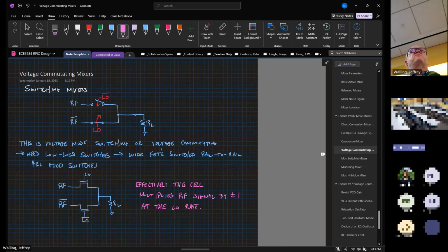So we would either bias the signal so that we didn't have to worry about that. And most of the time, that's what we do. We add some big resistors to put a DC level here, bias through a big resistor, so that we can set the common mode to make sure that the switch can always turn on and turn off. What I'm about to show you is that, and that's done, but you can also do a complementary switch.